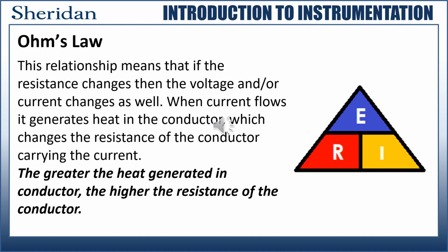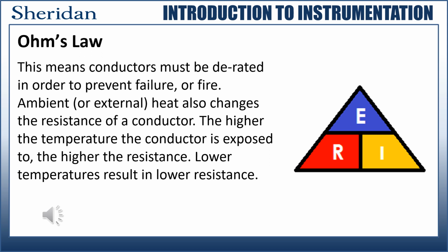Keep in mind that a conductor is also a resistor in a circuit. When current flows, it generates heat within the conductor. This then changes the resistance of the conductor carrying the current. Since conductors tend to have a positive temperature coefficient, the greater the heat generated, the higher the resistance of the conductor. The resulting change in resistance and heat means that conductors must be derated in order to prevent failure or fire.